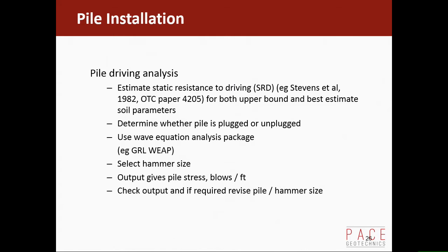Somebody made the point about driving the piles, and you do have to do a driving analysis. You've got to choose the right sized hammer for the job. We basically calculate a static resistance to driving, which in some ways is very similar to working out the axial capacity of the pile. Work out the resistance at depth as it goes down. We'll analyse whether the pile is plugged or unplugged, although in reality in most cases it behaves in an unplugged fashion for driving. And it's another case where you really don't want to do the calculation by hand. You want to do it with a program.